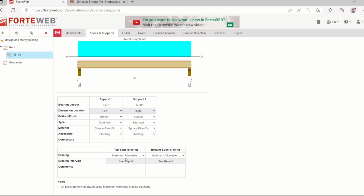And then bracing, just say maximum allowable here for the bottom bracing. But the actual design of this will be from the truss manufacturer. So all we have to do here is just a mock-up design of our truss so we can get the reaction and then link that load. Instead of the usual tributary and then applying that on your wall studs, that's fine. That's another option. I mean, actually, I did that before, but since you can link the load, I decided, okay, we'll just do a mock-up design. It's easy to do it that way rather than calculating how many it will carry every time you design the load.